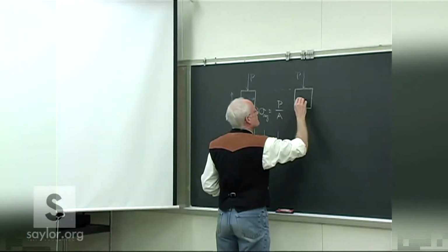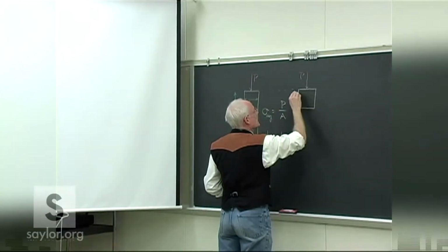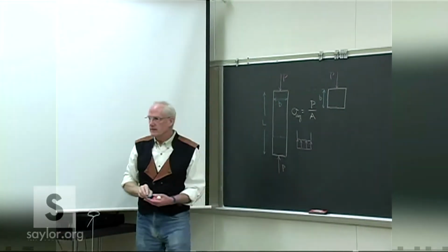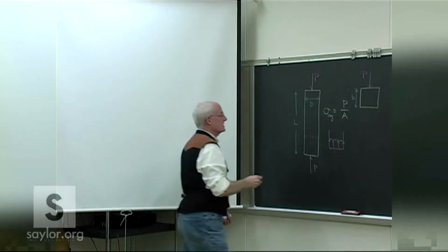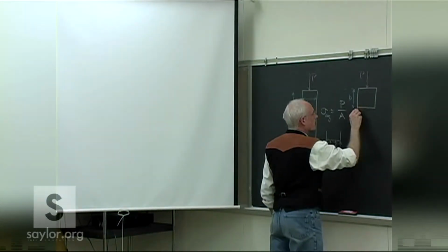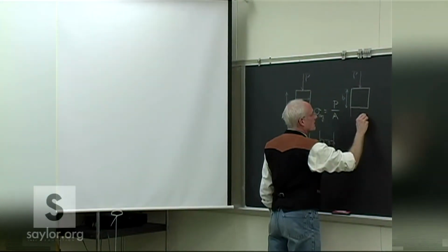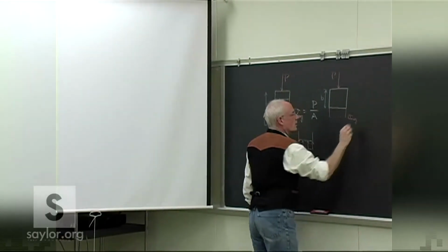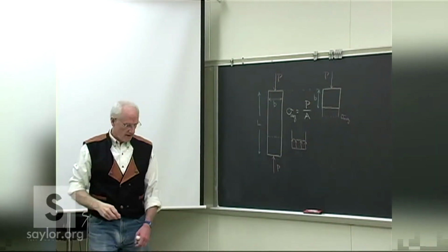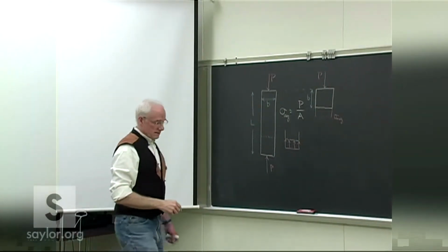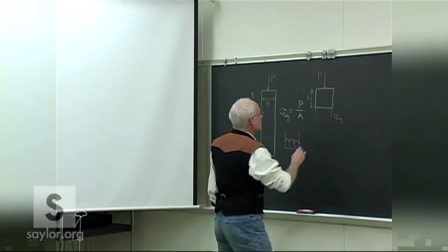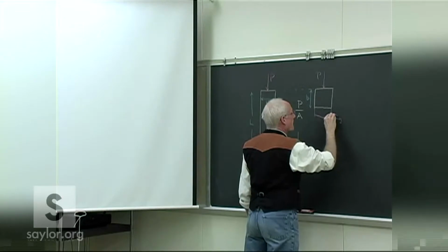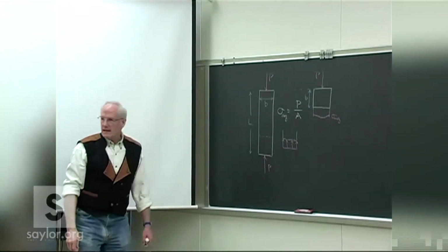So now we're at a depth of about B into the part. If we look at the true stress distribution, there's our average value we have been using. At this point about B into the piece, we get a real stress distribution of something a little bit like that.